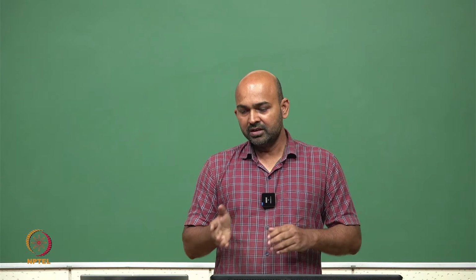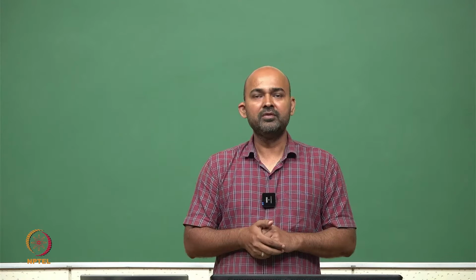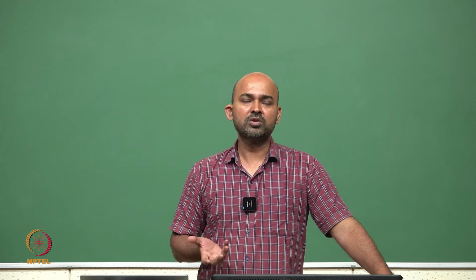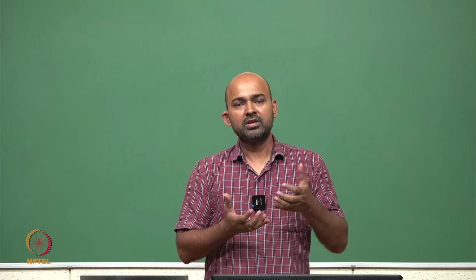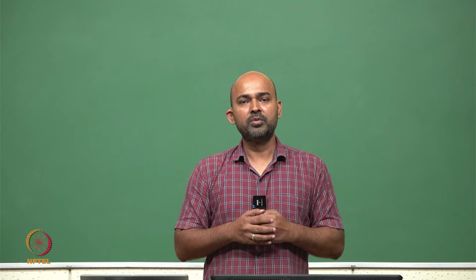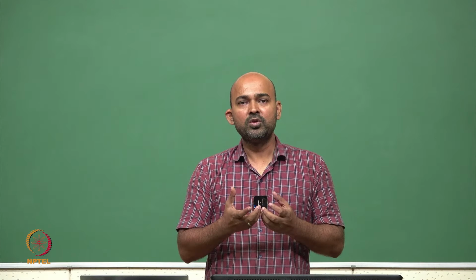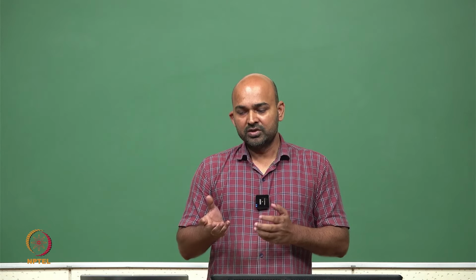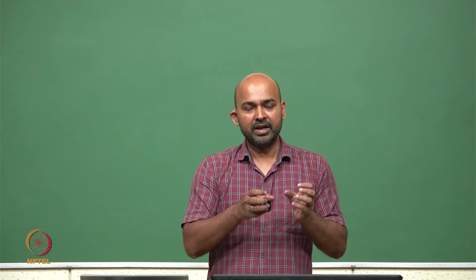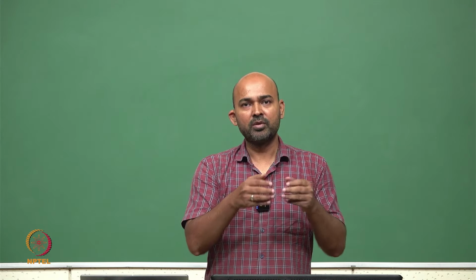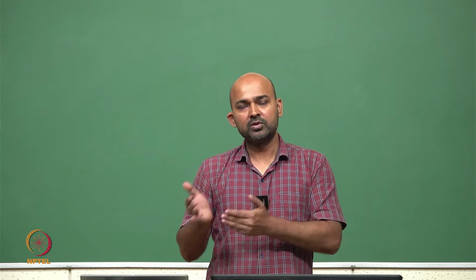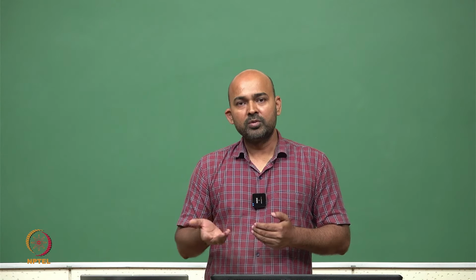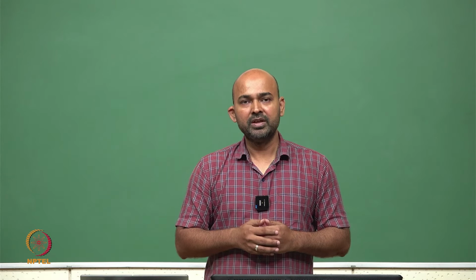So, today we have seen two very important circuits. One is the full adder, which is very widely used in digital design, and then we saw the mux. The mux is also a very important circuit which can be used for selecting one out of many inputs. Let us say we have 4 inputs and we want to select one as an output. So, we can use a mux in digital circuits. We saw that we generate the Verilog code, and when we simulate it, one is the textual format where we generate the truth table. That truth table we can check visually against the circuit, or we can see the output waveforms using GTKWave, which is again free software.